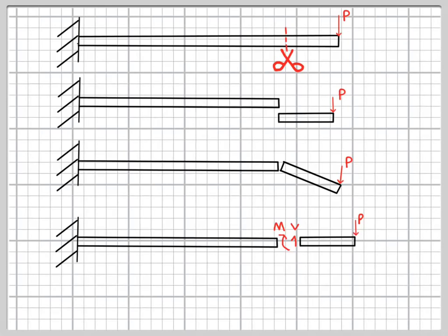Shear forces are normally given the symbol V and indicated by an arrow with just one head, and bending moments are typically given the symbol M. Now, because these are internal stress resultants, like an axial force in the beam, we have what's called deformation sign convention. With an axial force, we say tension is positive.